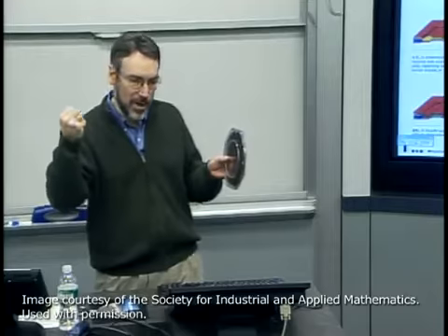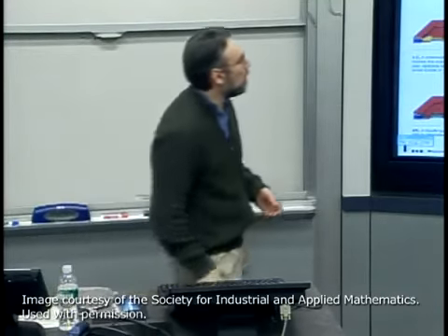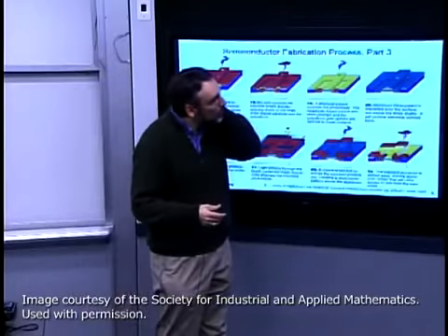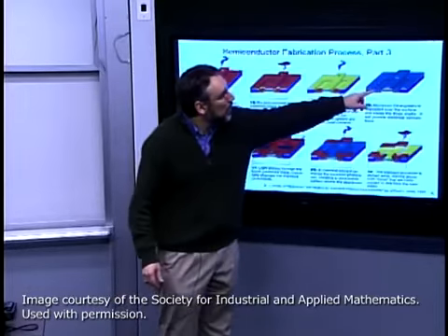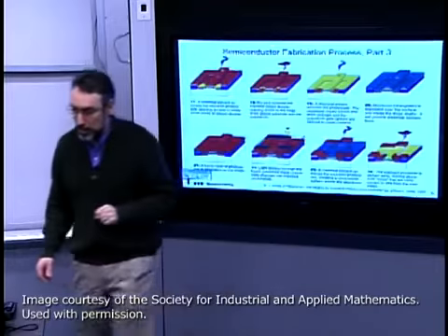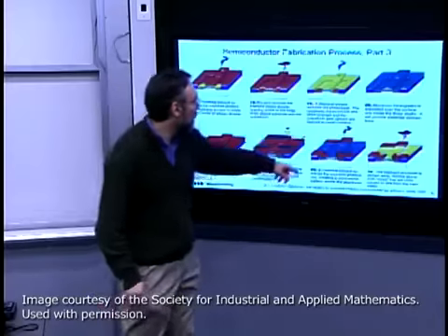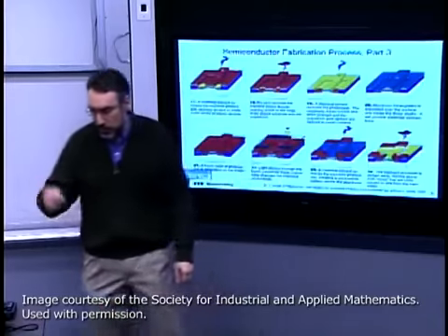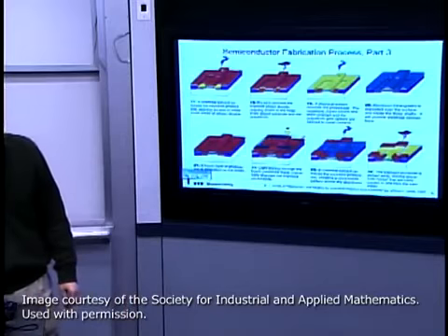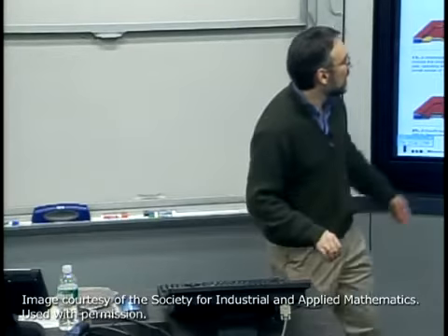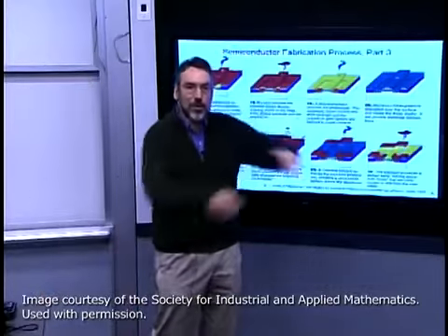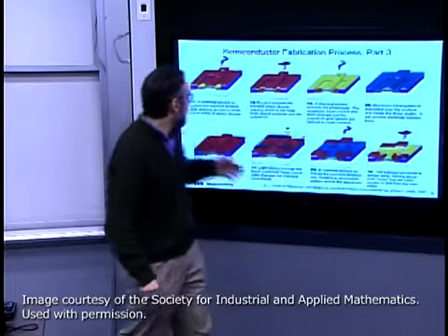such that either individual molecules or small agglomerations of molecules become very excited and trajectory through the vacuum and build up the layer on the surface of the wafer. So in this case, this is an older technology. They're talking about this being aluminum. I'll show you a little bit later that most of the most advanced chips are now using a copper interconnect, which has other challenges.